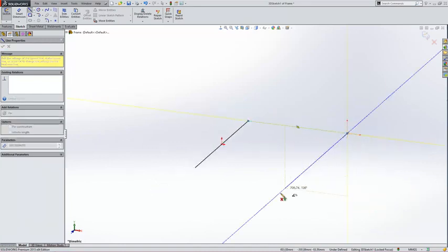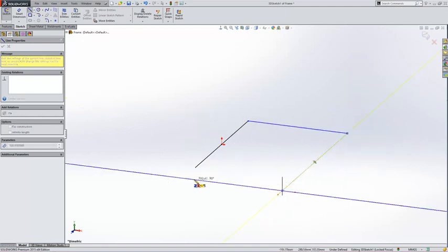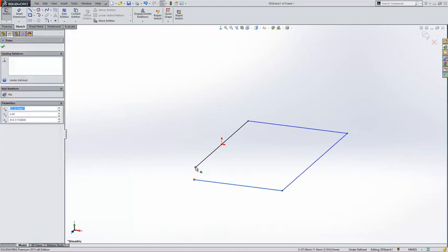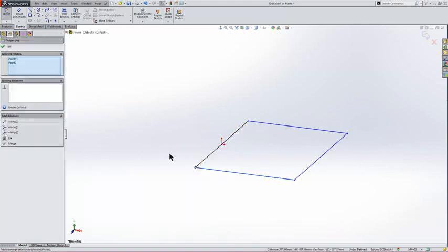Now I want to come down and create the Z-axis. Now we don't have a yellow line indicating that it's going to be placed on there. So we need to alternate. Selecting the Tab key on our keyboard, we can alternate between the axes. And we can place it on the Z now, followed by the X to finish up and close the sketch.